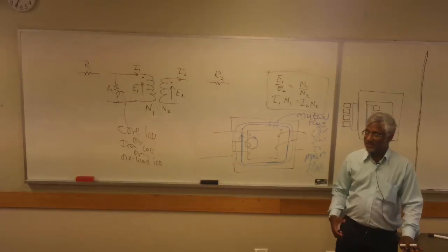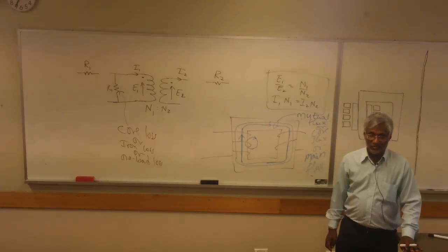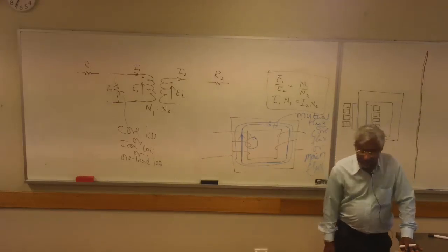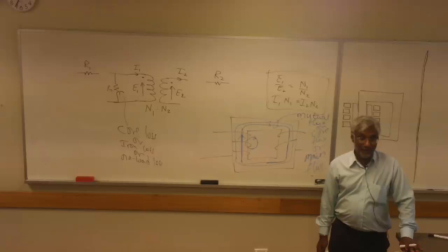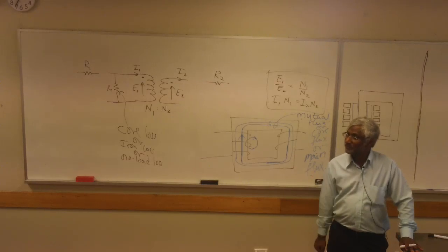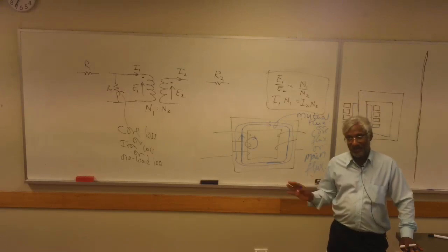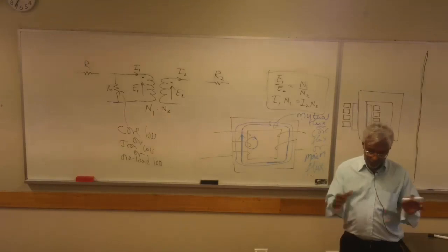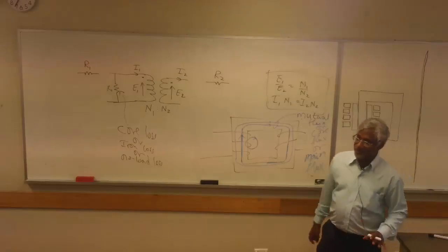That is what sort of flux density? Is it 5 Tesla, or is it 0.1 Tesla? Right. Silicon steel, these days, 1.8, 1.7? About 1.7 Tesla, and beyond that, you will hit saturation. It will depend on the grade of steel, but the rough number would be somewhere around that value.